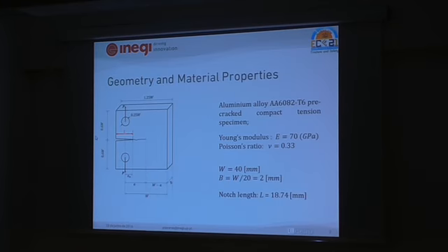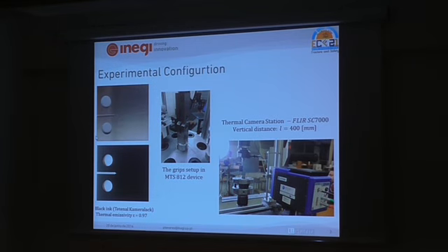We're already working on mode 2 specimens, but we started out with a CT specimen in mode 1, in the elastic regime, a typical specimen according to the ASTM standard.